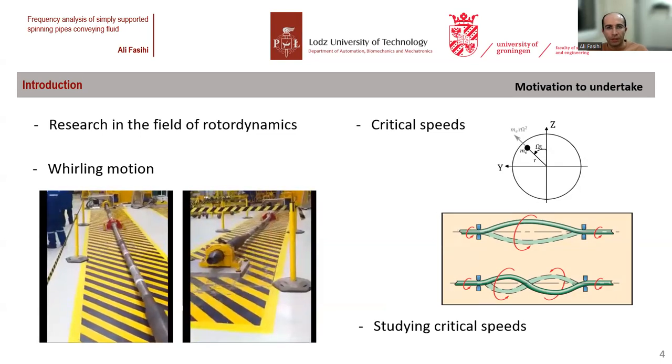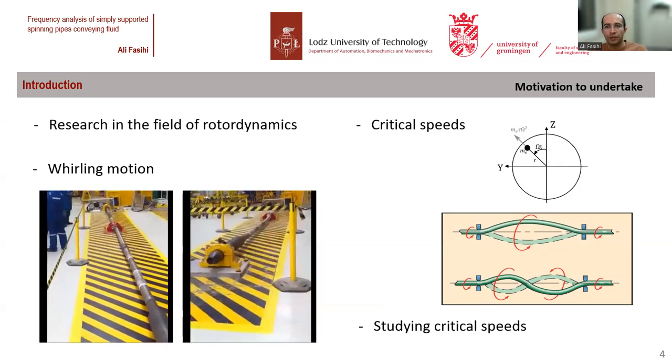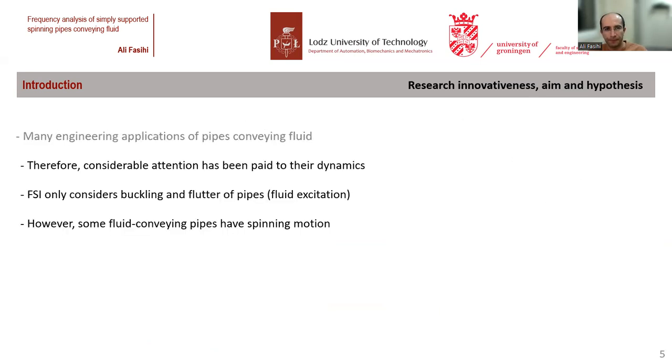In rotor dynamics, the rotating speeds that produce resonance responses are called critical speeds. At these speeds, the rotor has high amplitude motion in transverse directions. The major concern of research is to predict critical speeds and prevent their associated high amplitude motions.